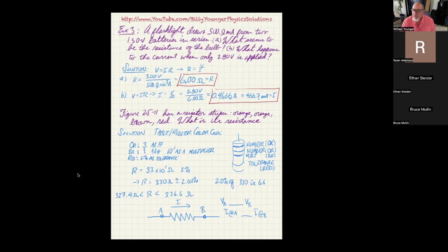All right, I'm getting ready to let you guys go so we can have a break till 5:30. So what's going on here is current flows from high voltage to low voltage. Since the current's going to the right, we know VA must be greater than VB. So I'm going to put a greater than symbol here. Now, the other thing is conservation of charge dictates that if I've got a certain number of coulombs per second entering A, I don't see any extra paths between A and B for those charges to go down.